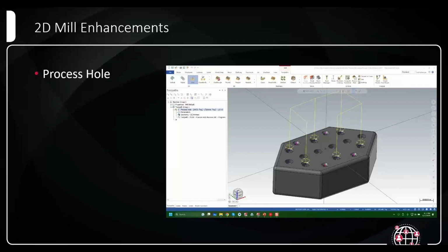In the rollout, this is probably going to be one of my bigger points of showing how to do this. But essentially, you just grab a file from before, and as long as you selected a solid hole, that part is important. You had to grab the entire hole feature, and they're the same size between 2 files. You can bring in that whole process into a future file down the road.